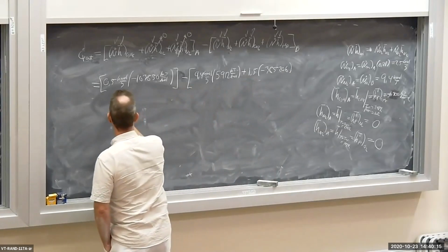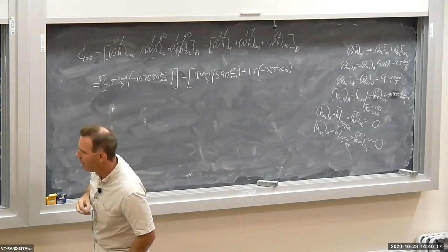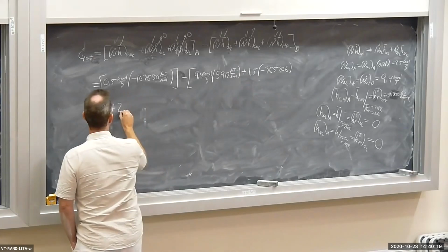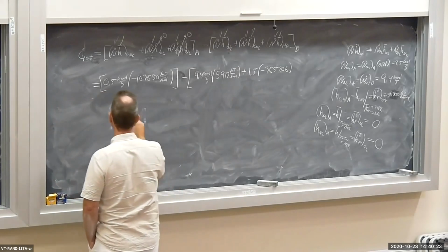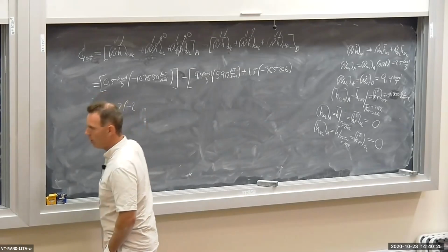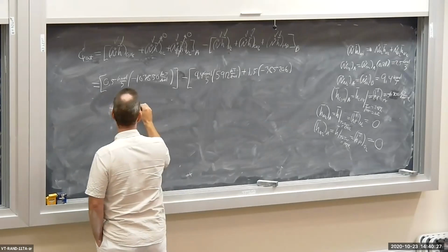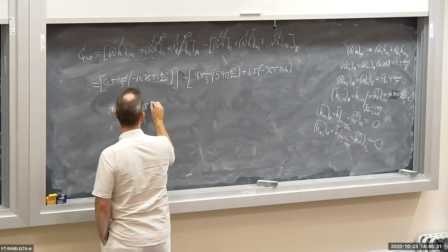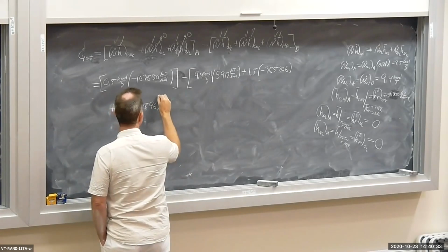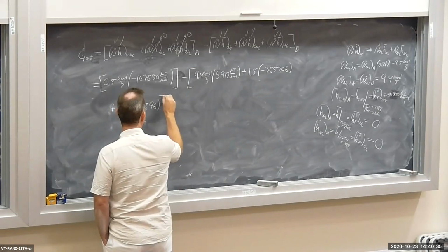And then I got the H2O, N dot for the H2O is 2 kilomoles per second. And we just calculated H bar for the H2O. That's minus 2348.96 kilojoules per kilomole.